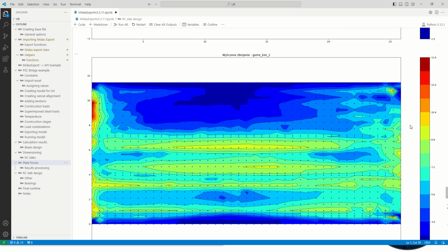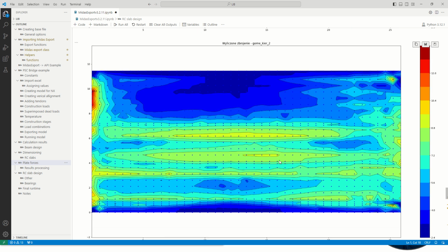And this is the amount of rebar in the horizontal section. Here we can quite well see the area where we have the live loads, the roadway. Here's the pedestrian area. There's no pedestrian load on this pedestrian area on this side, and all of this is done with the built-in load optimization of the lanes.